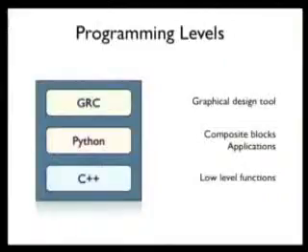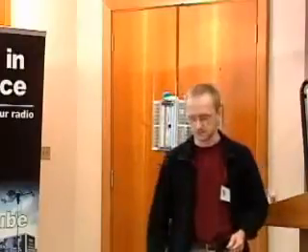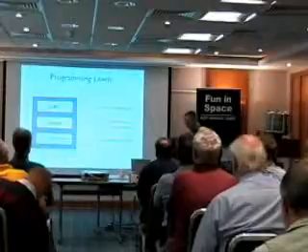They prefer writing Python applications because it's easier, and it doesn't cost anything in terms of efficiency, because what they do is connect all the blocks that have been implemented in C++, so there is no penalty. If you're like me and even lazy to write Python code, there is a graphical tool called GRC, the GNU Radio Companion, which allows you to sit back in your chair and design these flow graphs in a graphical environment. And we'll take a look at that in just a moment.